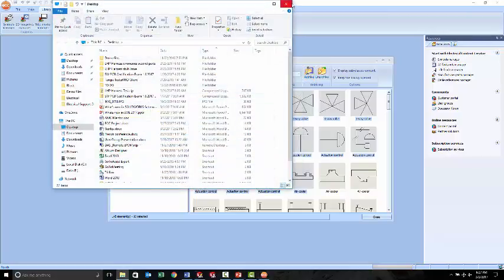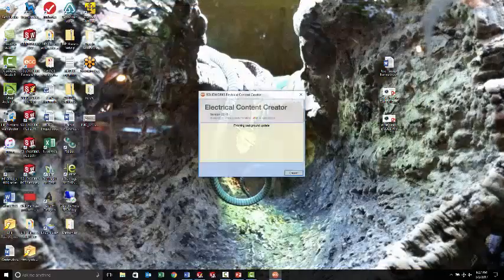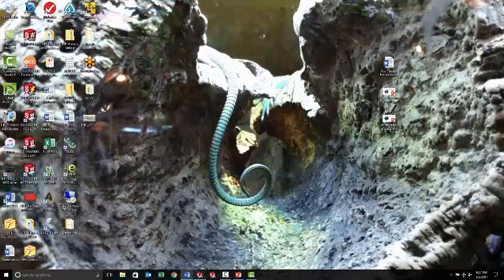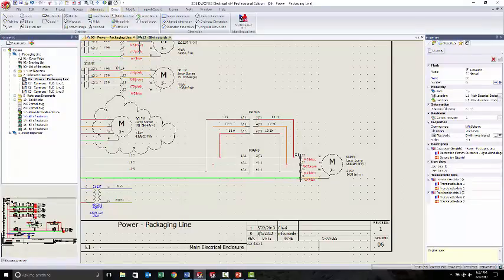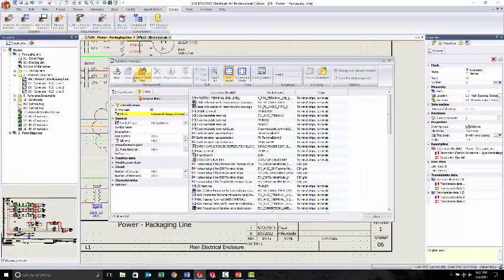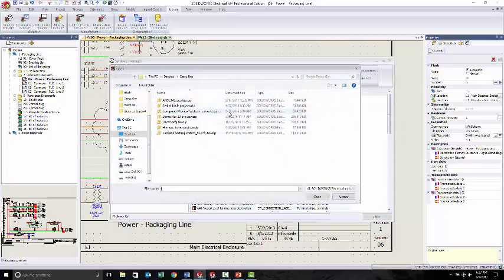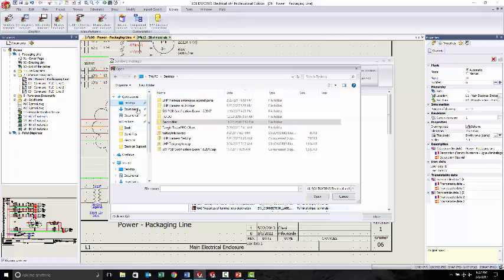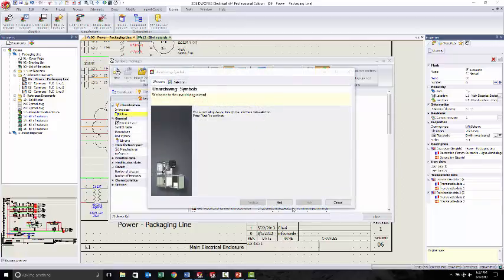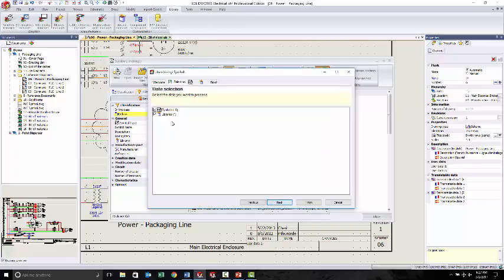From this area, in my electrical, I would go to the specific library for my symbols. And I'm going to unarchive that specific file. I don't remember where I put it. Hopefully somebody saw where I put it. I put it under test. There it is, test of symbols, TEW zip. I simply say OK. It will then see that I've selected 16 symbols.